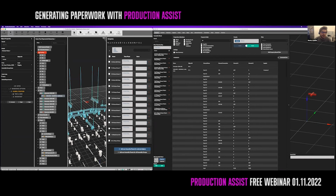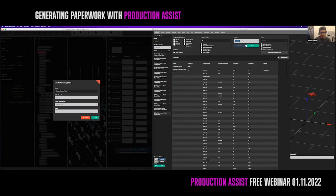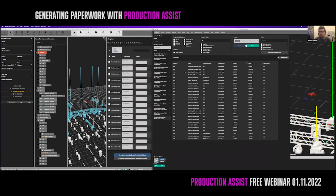For this, again, I right-click on the trussing assembly group and tell it to create an assembly sheet for this specific truss line. I can use the preset for this, for example, a hoist markout list extended. I'm pressing OK, and it will generate this list. I activate it, and now I'm only seeing all the hoists in there. I can sort them by object ID.